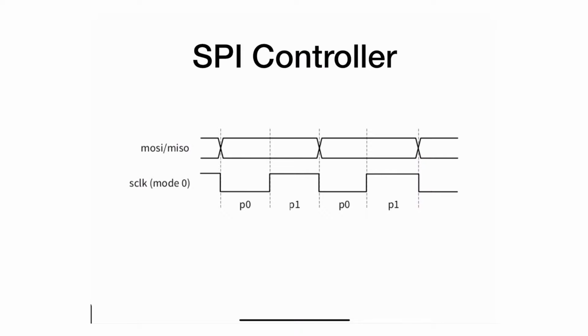Because the slave select signal is not really directly related to the master, even though it's generating it, it's really not that difficult to generate. We're just going to implement it outside the controller in a different mechanism. So we will only focus on the controller's main functionality, which is just shifting in and out data bits bit by bit. And this is basically what's explored in here.